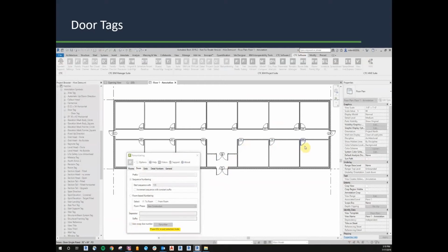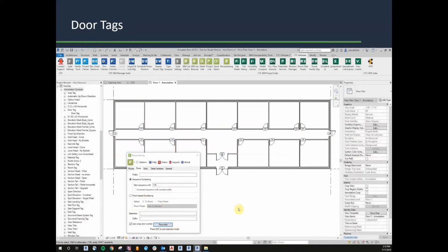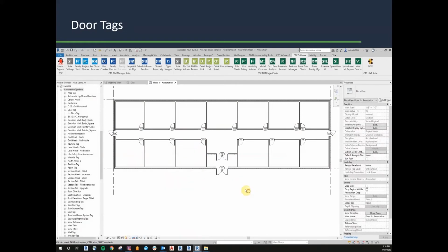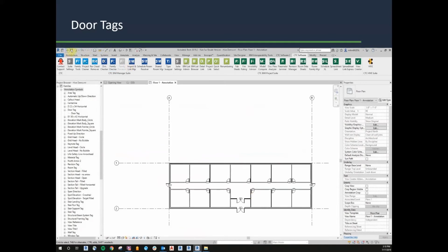And if that number already exists and it's assigned to another door, it grabs it and swaps it without ever giving me that warning pop-up that we would get to cancel, well, in this case, probably 16 times in a row otherwise. And you can see that Revit steals the focus while a renumbering tool is sort of intelligently staying in the foreground. And this is the way to renumber doors, rooms, grids, and views inside of Revit.